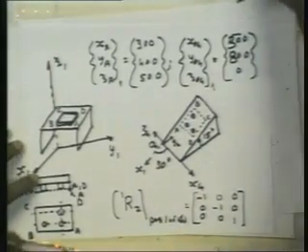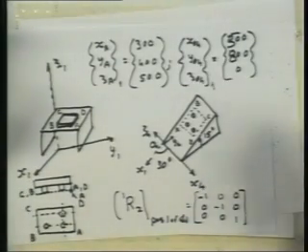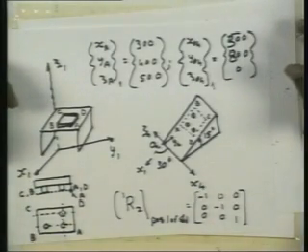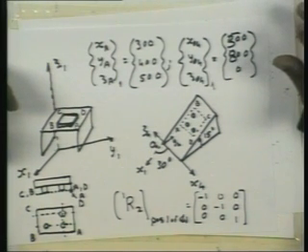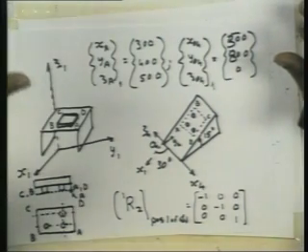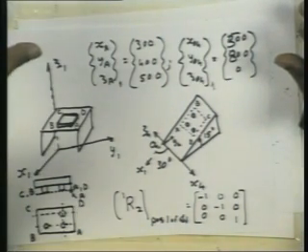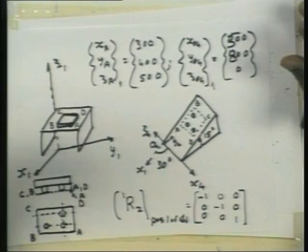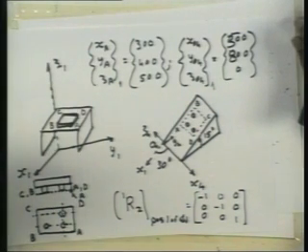Okay. Fine. Now the exercise is to find out the location of the end effector just before gripping at the first position, and to find out the position of the end effector just before we are going to push the pegs into the inclined plane. Okay, and I think we have specified enough to get to that. We can use the homogeneous transformation matrices for calculating it. Multiplying 4 by 4 matrices takes time, so you can do it on a computer very quickly. Fine. So complete this exercise. In the next class, let's see what the answers are.